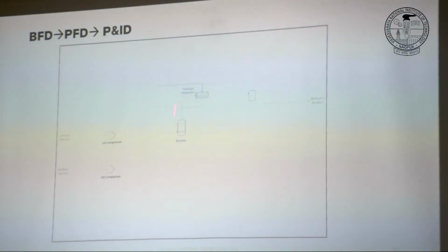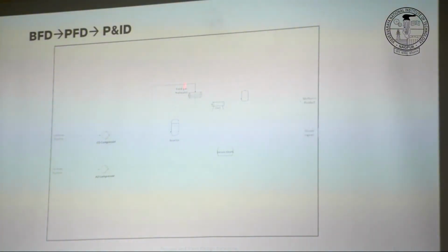So you have a hot stream here at 300, 320. We have to cool it to 30 to condense our methanol. And then you have one or two reactant streams which we need to heat up from 30 to 300. So one cold stream, one hot stream. Remember this TQ diagram. Based on this, we can use this feed effluent exchanger and recover energy. We'll recover energy up to maybe, if this stream is at 30 degrees, this product stream can be maximum at 50 degrees, 60 degrees based on delta T.